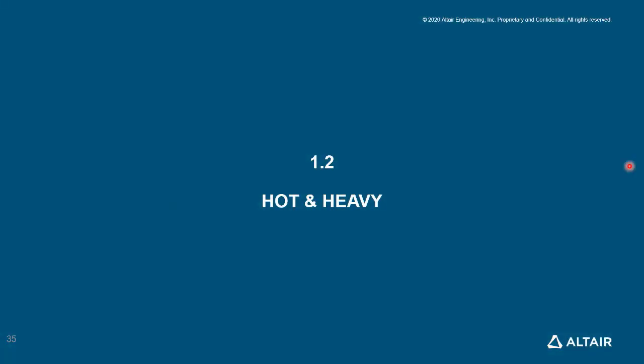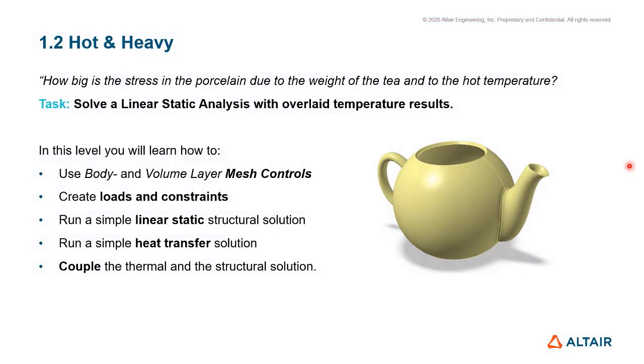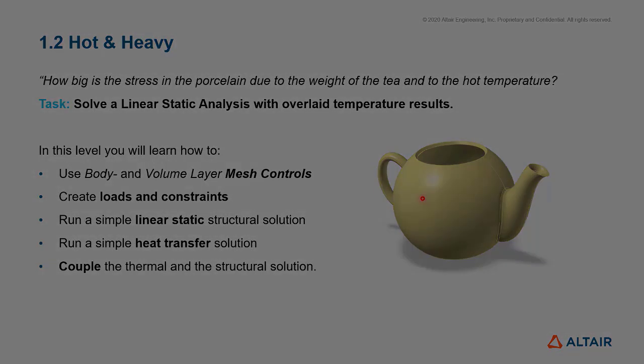Going into SimLab, let's see how this workflow that we've talked about in terms of physics problem, mathematical model, and FEA workflow goes into this software right here. In our demonstration, I'm going to use this simple model. It's not even an assembly, but for the purpose, it will be enough. In my case here, I'm going to do a linear static event and also heat transfer. And then I'm going to overlay the temperature results from my heat transfer to my linear statics.